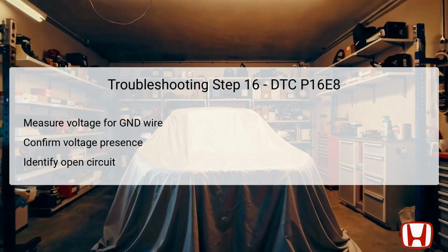If battery voltage is observed, it may indicate the harmless operation of the corresponding wiring system. Nevertheless, absence of voltage here signifies open circuit issues within that line. Depending on voltage checks, targeted repairs can then be applied, assuring effective communication pathways within the electrical systems.